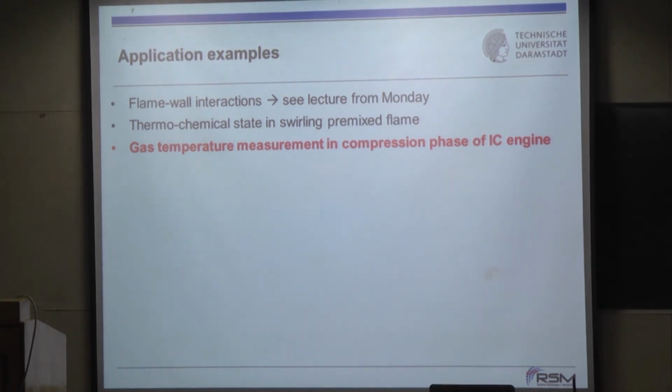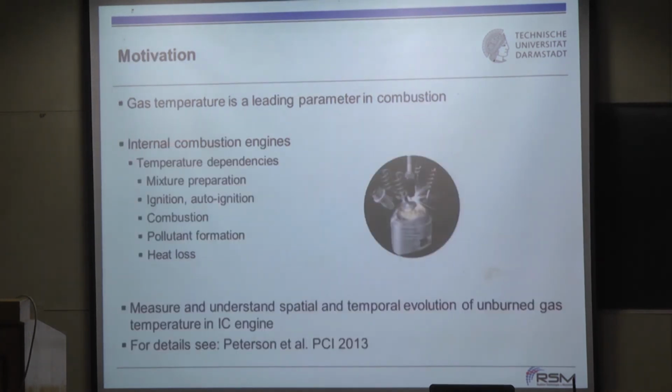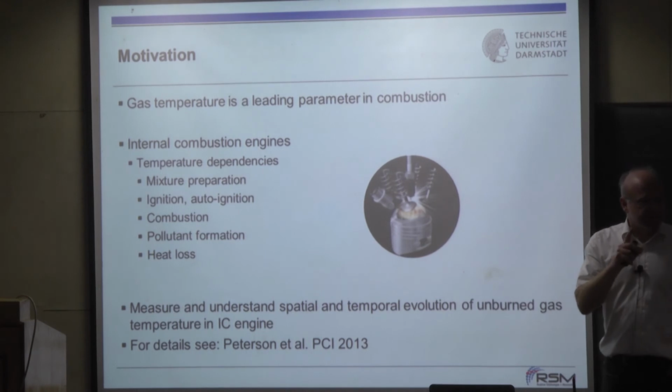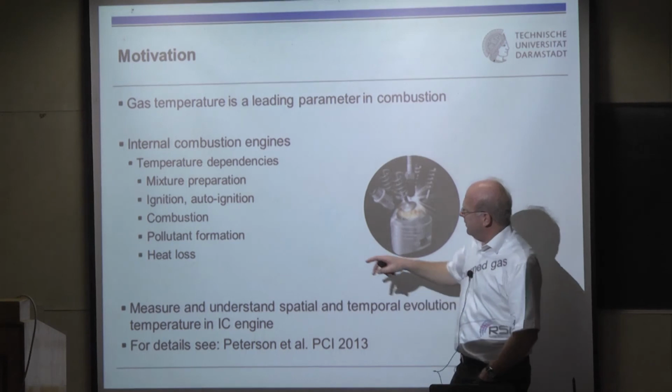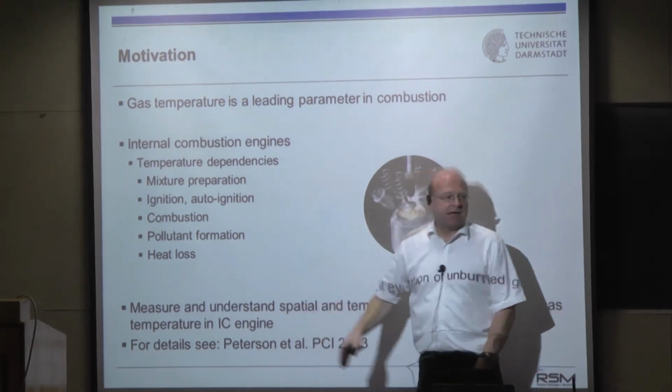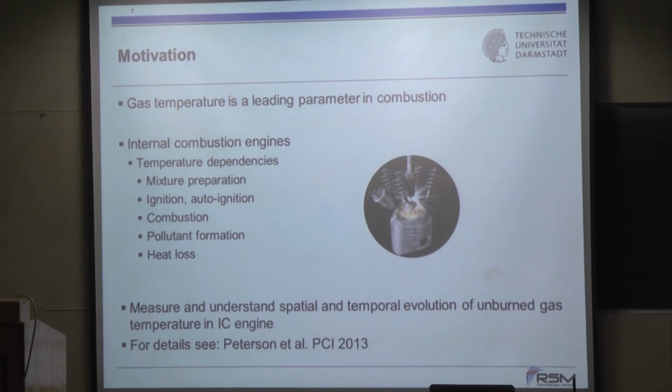Okay, then we go on and have a look into the gas temperature measurements in IC engines. For obvious reasons, it is very important to have that, and maybe I refer back to the question. Of course, the technique I'm referring to is again the toluene LIF we discussed briefly. It is, for example, very important to understand autoignition. If you go for HCCI engines and want to understand what's going on there, then you would like to have a very accurate and precise measurement of the gases during compression. That is something where you need techniques that give information about it.